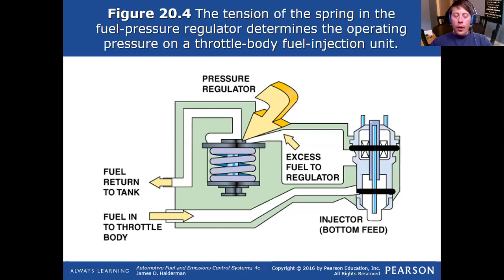And so if we think about a computer trying to add fuel or trying to subtract fuel, so plus on fuel trims, minus on fuel trims, that's all based off of that pulse width that it's going to command. It's all based off of these factors, these norms that it's assuming are correct. And so I'll try to explain that a little bit better.